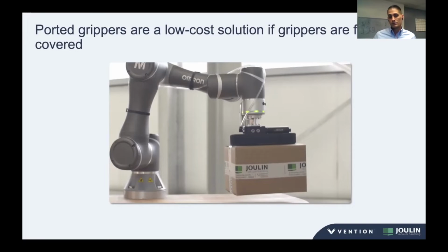If you're not familiar with collaborative robots, they are able to move around, and Patrick touched on this just a little bit, but you can work right beside them, which makes them very unique. The reason they're unique is that they can actually come into contact with you, and then they come to a stop because they sense that they've come into contact with a human. And so we've made these grippers to where they're very safe. They're made of 90% foam and some carbon fiber components for the structure, so that they can be very robust.